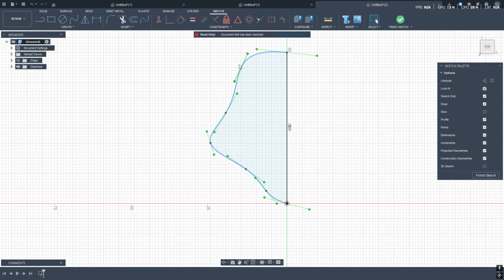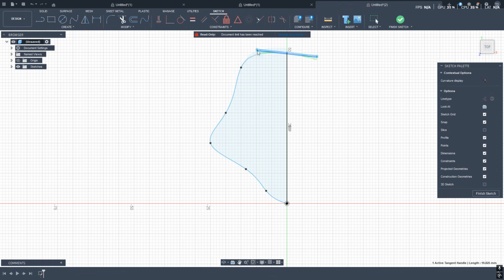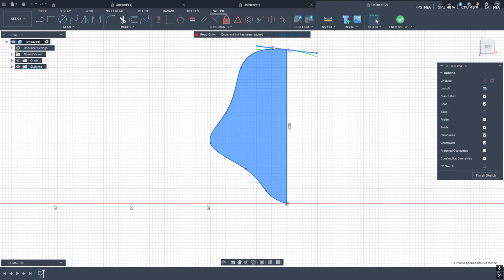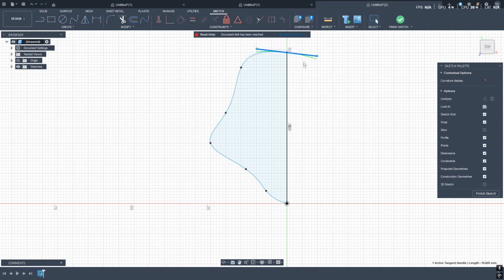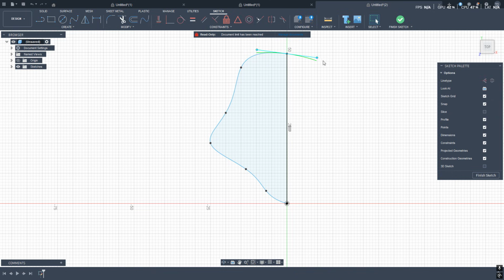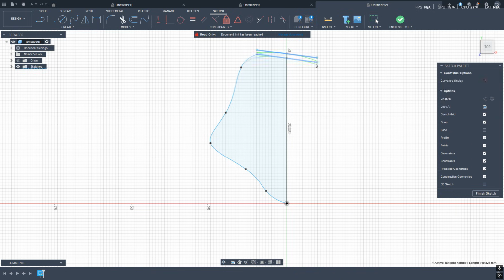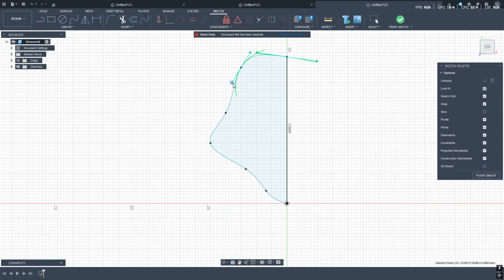And then every single point you created has two options. It has this bar, and if you lose it, you just click the point and then you can grab the entire bar and move it up and down. Or you can grab one of these points, and if you twist it, it will twist the shape, and if you drag it, it will drag the shape.